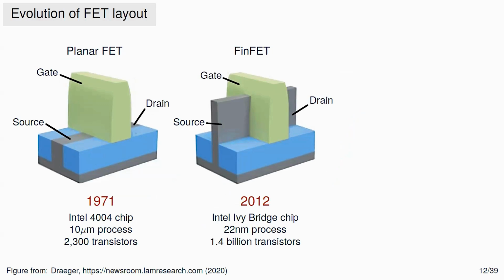To do that, you just have more of the same, but you make them smaller. So the idea is to reduce the size of this little bridge here, which is basically the channel. And now the typical channels 10 years ago were of the order of, let's say, 20 nanometers. Okay, silicon has a unit cell of half a nanometer with 2 atoms in that space. So that means that there are maybe 80 atoms across from here to here, right?